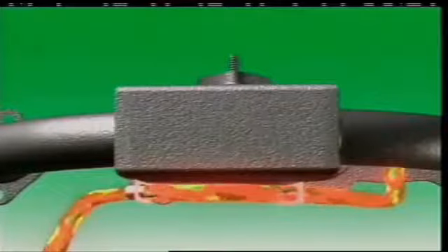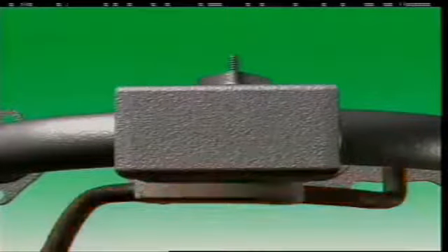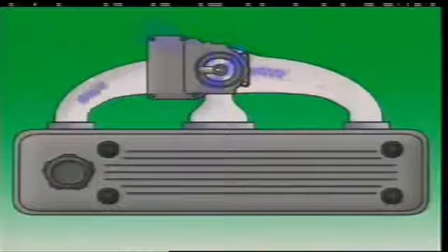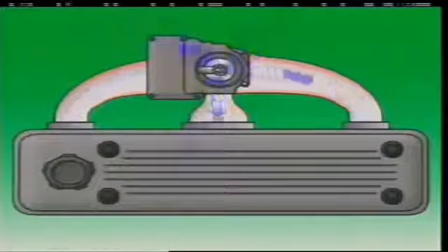Vaporization is also assisted by heating the intake manifold, normally by circulating hot liquid coolant through passages in the manifold. If a manifold is too cold, fuel condenses on its inner surfaces, which will create a lean mixture and may cause incomplete combustion. Carbon monoxide and hydrocarbon emissions are highest from a cold engine.